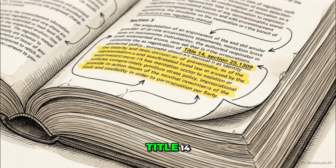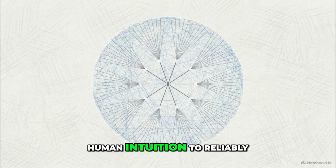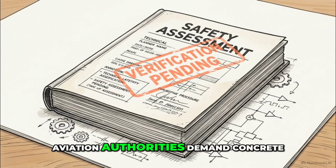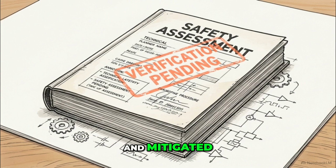Title 14, Section 25.1309 of the Code of Federal Regulations mandates that no catastrophic failure condition can result from any single failure. Modern aircraft architectures are too densely integrated for human intuition to reliably catalog every possible failure state. Aviation authorities demand concrete mathematical proof that all credible failures have been identified, understood, and mitigated.